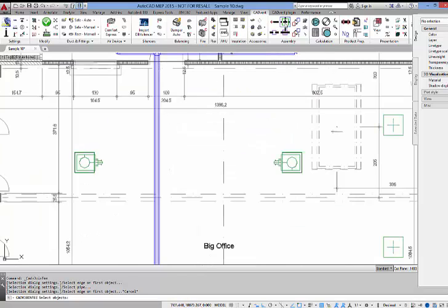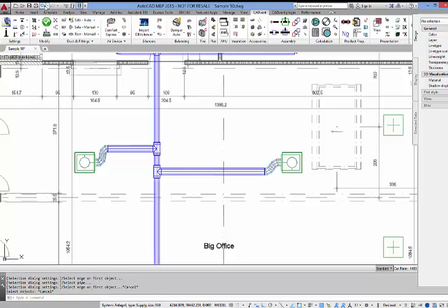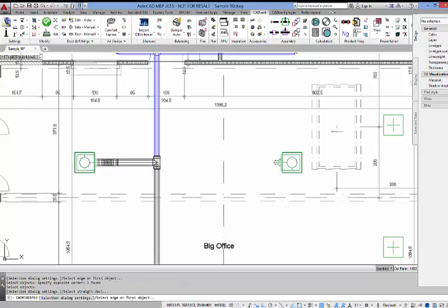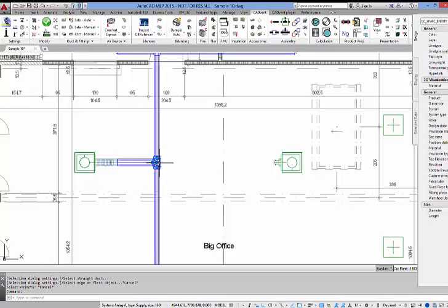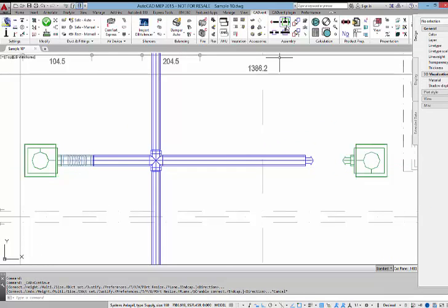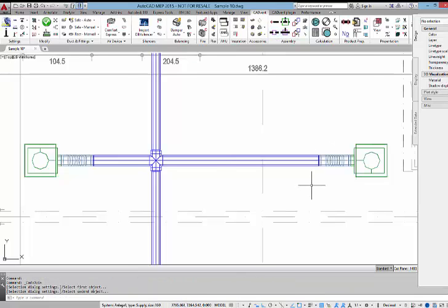So how do we connect here? It's the same way. I can do it in 2 ways. First of all, I could say 1 T-piece here and 1 T-piece here. Once again, 1 T-piece here. So that's one way to do it. Not so nice, but possible. The other way is we can do it immediately, that we say this one here should be connected with a T-piece here. Then we change the T-piece into a cross piece, going up to here, and then the join endpoint command that we know already connects here.